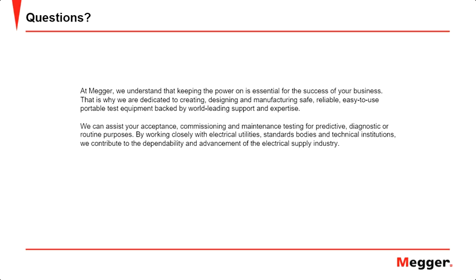DAR is the dielectric absorption ratio. For people who are not familiar with DAR testing, you use an insulation tester and determine the ratio of your 1 minute to your 30 seconds. That's your DAR ratio. It is a very short test, and it's not as prevalent or as stressful to the cable compared to a VLF. We are talking about a completely different ball game.